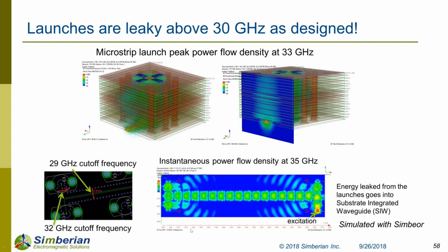In your conversations with your PCB vendors, it sounds like the one that worked on this board was a pretty decent one. Have they stated any limitations to the amount of stitching vias you can place around the signal via, or any manufacturing tolerances to keep in mind when you're trying to create this localization? Well, when it comes to stitching vias, no, you can place them, and they have some manufacturing guidelines, for example, how close vias can be placed together. But when I did the simulations of the launch, the result is dependent on which boundary conditions you use. If you assume there's no leakage outside this air box, then you don't see these resonances, but they happen there. So you have to really design your interconnects in such a way that you can accurately simulate them.